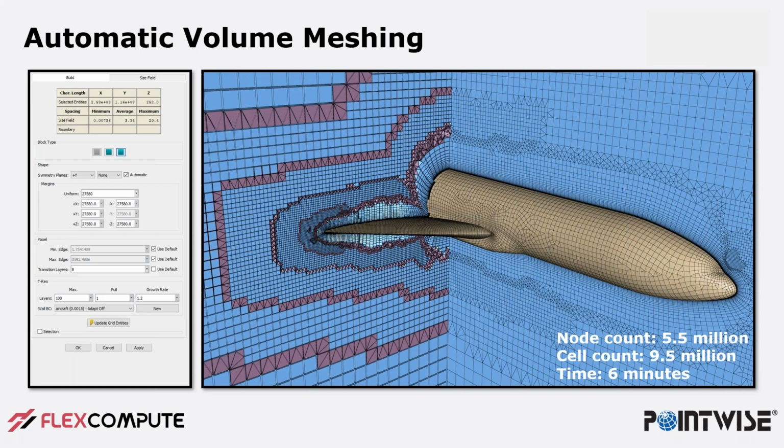It's a half symmetry model. You can see that symmetry plane domain over on the right-hand side, and you can see the volume mesh matching it precisely. There's no buffer layer of tetrahedra between the volume mesh and the symmetry plane. And the real advantage here is that we can actually mirror this on export.